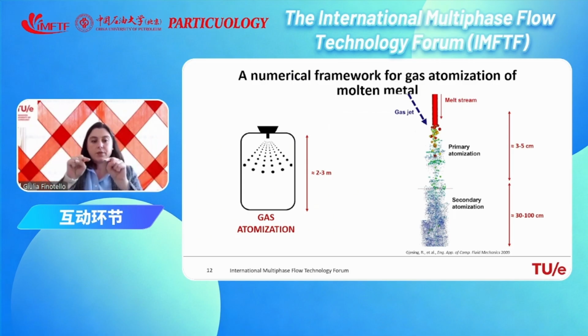So the melt is recirculating, touching the nozzle again, and you have this recirculation area very much on top of the nozzle, and then only part of the stream is able to extend and proceed at a lower height of the spray. In terms of dynamics of this interface, there could also be some filming, so some accumulation of melt really at the top of the nozzle.